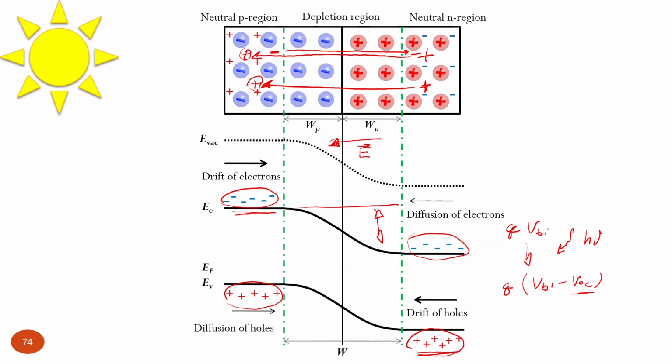And that will be our forward bias under open circuit conditions. So this barrier drops, so it becomes smaller, and it means that diffusion of majority charge carriers will increase significantly, because we have exponential dependence between the diffusion current and the height of the potential barrier.